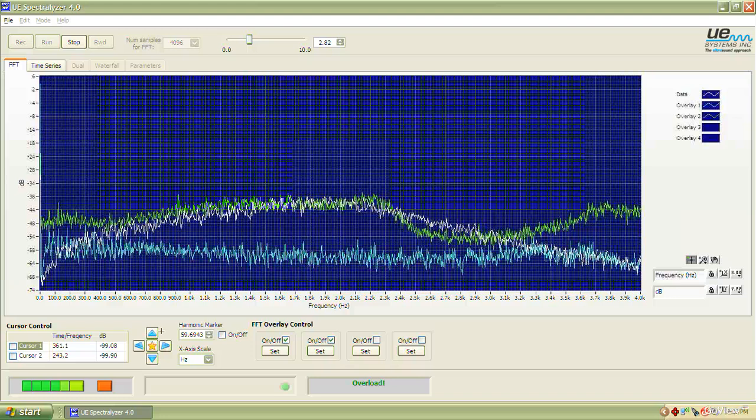If I wanted to zoom in, I'd put a lower value. So I'm going to put 10 to 1000 hertz. Now it's spreading that graph out, and I can really see that nicely. All right. Same with the peaks. My dB axis range is -70, which I don't want to go too far beyond, because you see that peak there is close to that -70 bar, but the max is -30. And the max we're seeing here is just a little above -50, around -49.